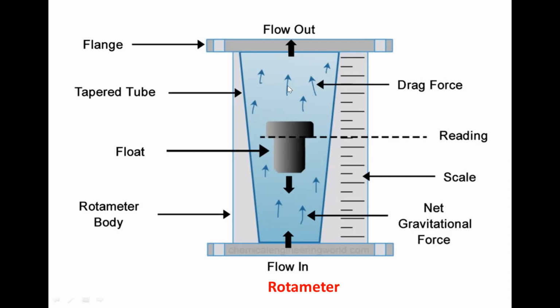But when the upward force, that is the drag force or float force due to the fluid movement, is balanced by the gravitational force downward, then the float will settle at a particular place. That is, this net gravitational force causes this float to settle. So this is a wonderful instrument for measuring the flow of a fluid or quantity. It is a very simple device and can be used by anyone. You don't need much skill, and even the cost is very low.